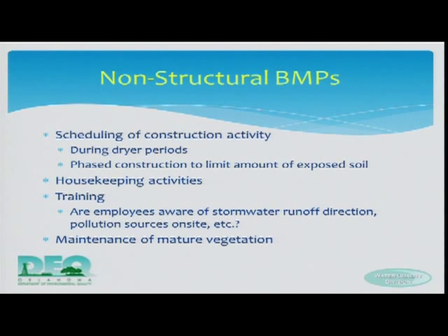Non-structural best management practices include training, telling people what this stuff's out there for. They may or may not be aware of what they're doing whenever they're destroying your controls. But making them aware of it is something that can help you out a lot. Like I said before, scheduling is a non-structural best management practice. Also, keep things cleaned up around your site. Keeping a neat site is important.